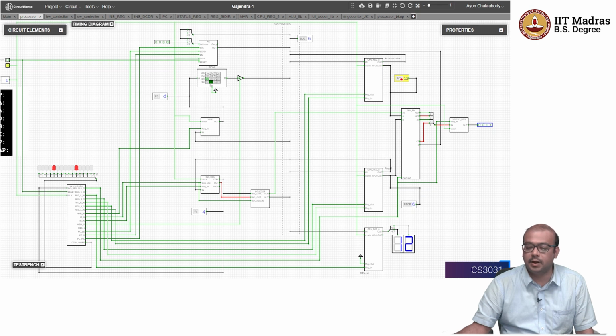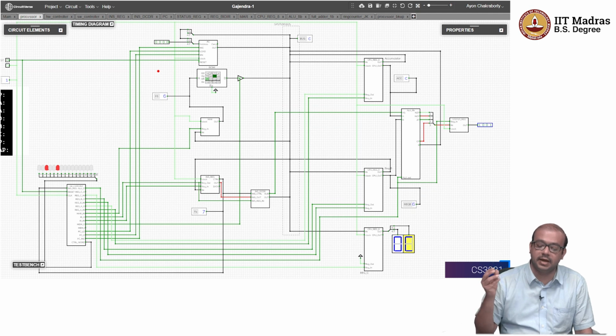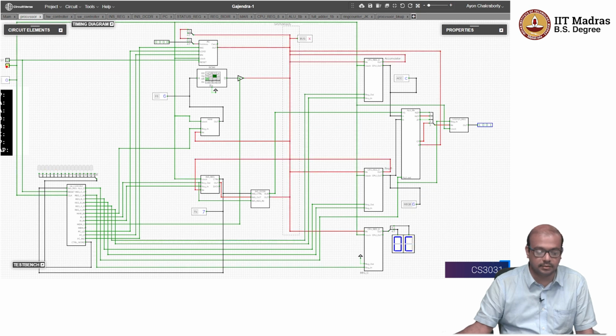So this is going to contain how much? 18 minus 6, which is 12 in decimal or C in hexadecimal. Okay, so C. Again a display. I'll do a display. Now my display contains C. Okay, display contains C. So that part is also over. Now I am going to do the execution of 4E. 4E is basically again going to take out the value 4 from C. Okay, the answer is going to be 8.